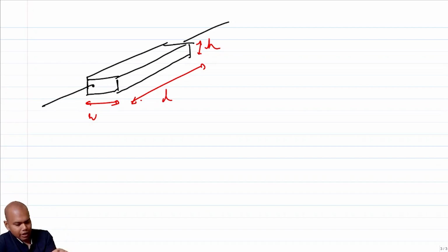So now, for a given topology or a given piece of wire, if I have to increase or decrease the resistance, what should I do? I have to increase the W, or reduce the L, right? So essentially, just like a MOSFET, the W and L individually are responsible for setting the resistance, right?